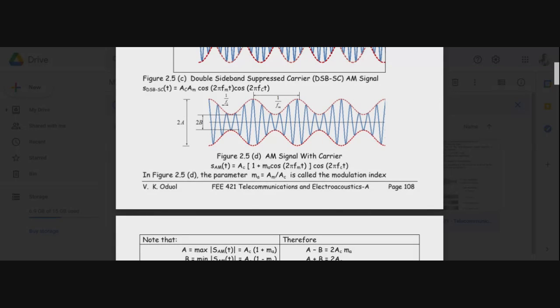So in what is called the conventional amplitude modulated signal or system, the amplitude, the envelope, which is the outline, stays on one side. It does not cross the axis. So in this diagram, the envelope detector will just pick the positive side of that outline as the output.